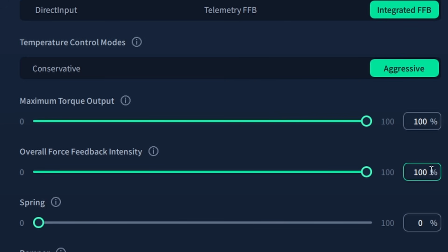Second, we've got the overall force feedback intensity. This controls how much of that torque is regularly sent to your hands during standard flight maneuvers to keep the signals from clipping. Here is your first major configuration guardrail. For a Cessna 172, lower this slider to 40 to 50%. A real Cessna has a relatively light unassisted mechanical yoke. If you leave this too high, the stick will feel unrealistically heavy, like you're wrestling an iron bar just to make a standard rate turn.